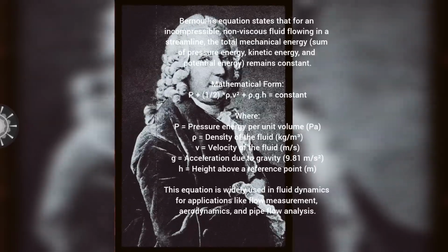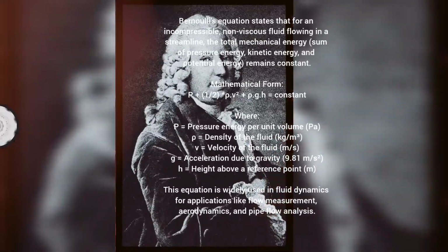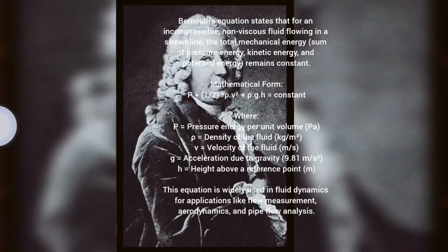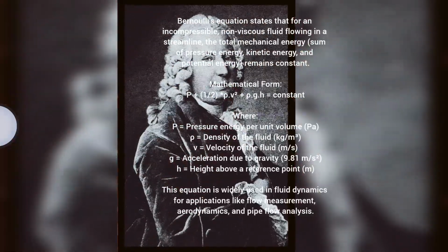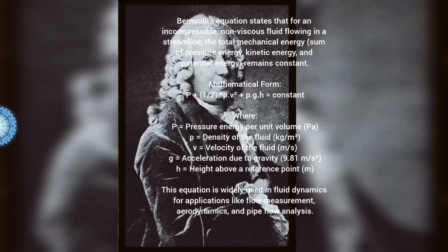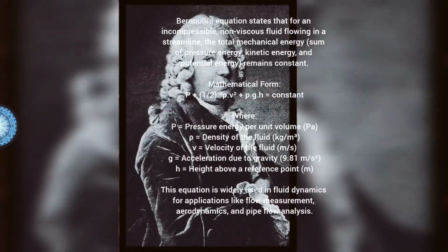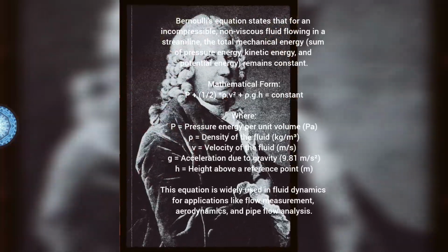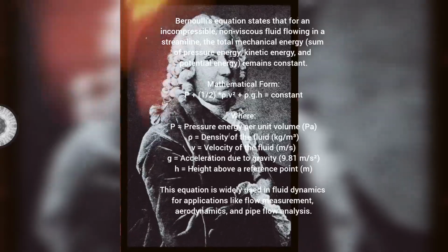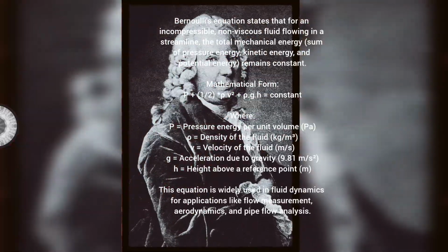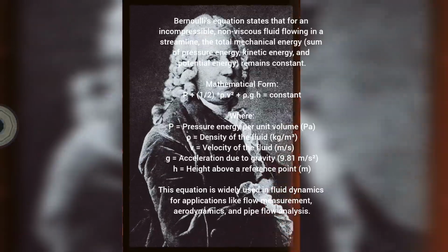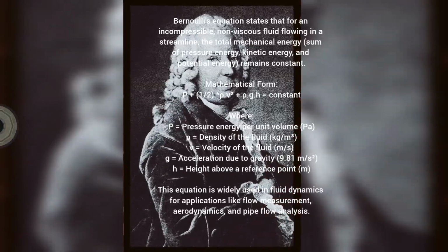We were talking about airplane lift earlier, and I'm still kind of hazy on how Bernoulli and Newton's third law work together there. Yeah, let's break that down. So picture that airplane wing again, curved on top, flatter underneath. Got it. That shape is super important. As the wing moves through the air, the air's got to flow over both the top and the bottom. Right. Now, because of that curve, the air going over the top has to travel a longer distance to reach the back of the wing compared to the air underneath.